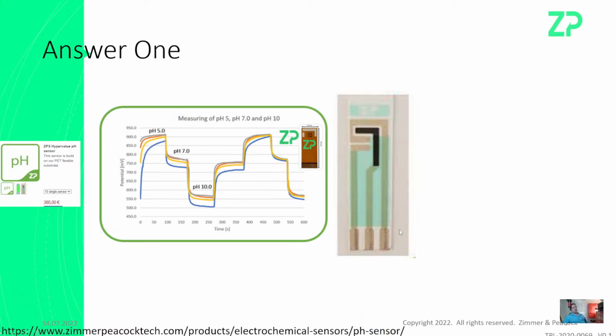If you do get hold of these sensors, you actually just have to measure the voltage between 2 of the connectors here. This pH sensor is basically a voltage generator, and you have to measure the voltage between these 2 parts here.